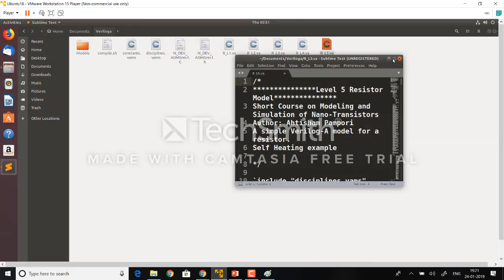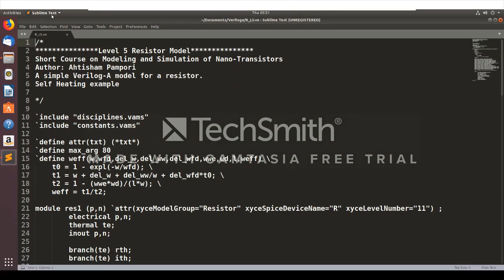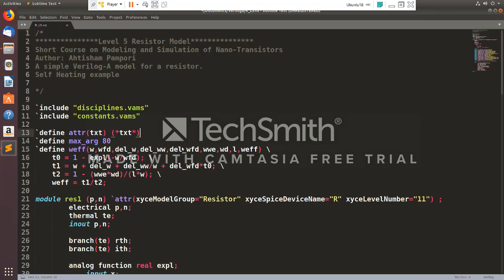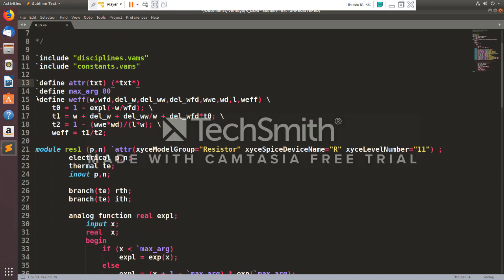Now we have the last one. Okay, yeah. See now, I didn't take the exponential function. I took the V effective function. I took V effective, and instead of defining it inside, I defined it through a macro outside. Okay, this is how you define a macro outside. See, there's nothing behind this backslash. There's a space between this and this, but there's nothing behind the backslash. Okay, all of this is a single line. This is how you define a function in a macro.